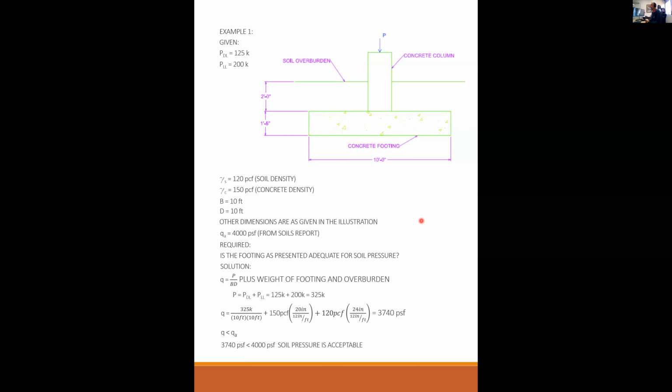It should not keep sinking because soil settlement is a time-based thing. So it takes time to settle, but after so much time, it really should stop settling. It should catch itself.